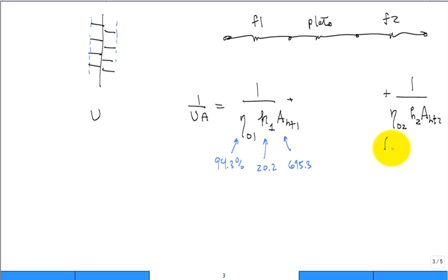We found that this one was 658-ish, roughly. The convection coefficient was around 12.3, and the overall efficiency was 90.3%. So you could do it on the 1/24th, or you can do it on the whole thing.